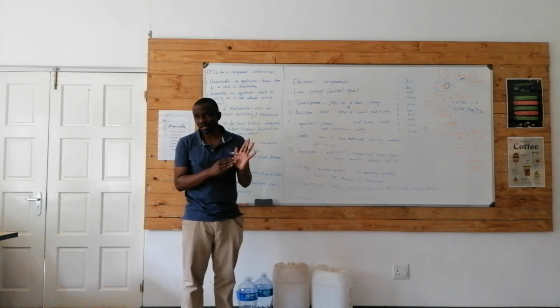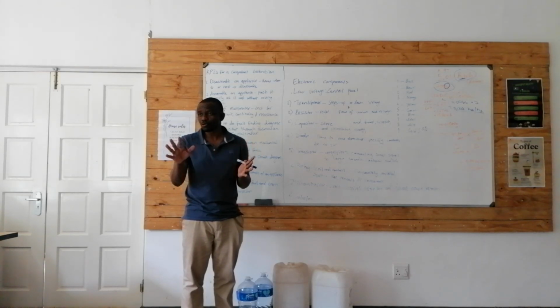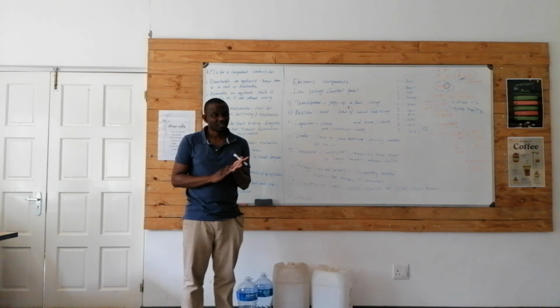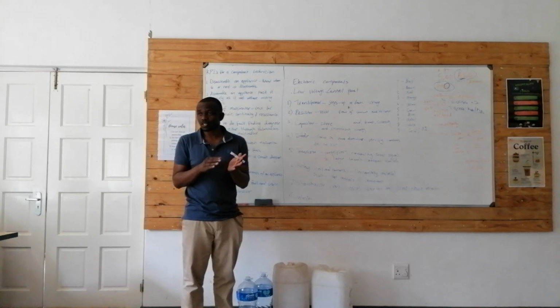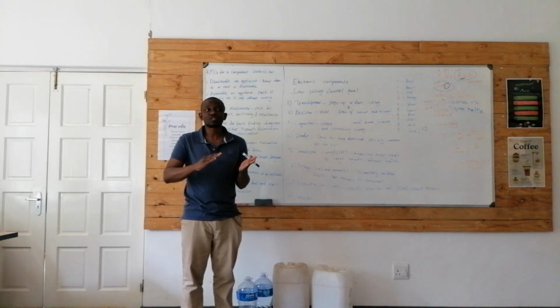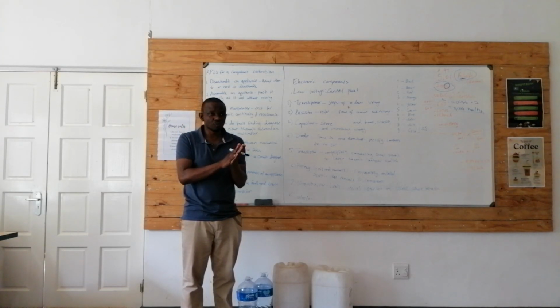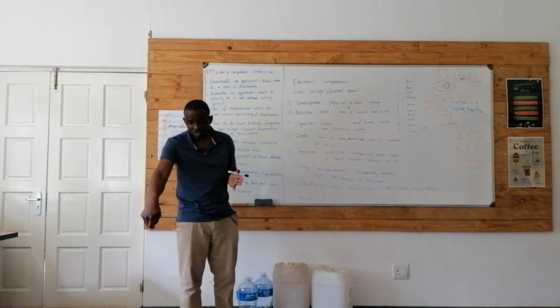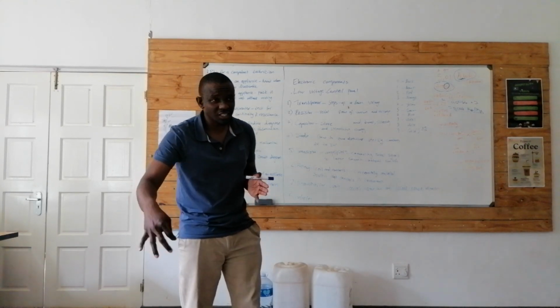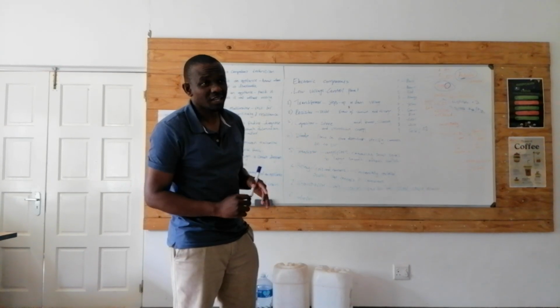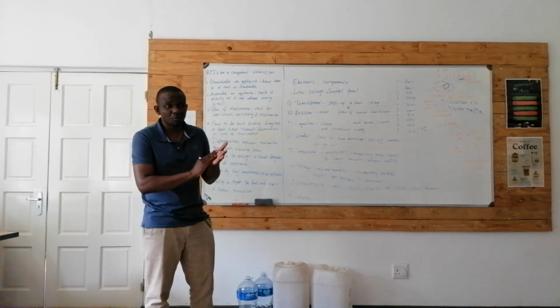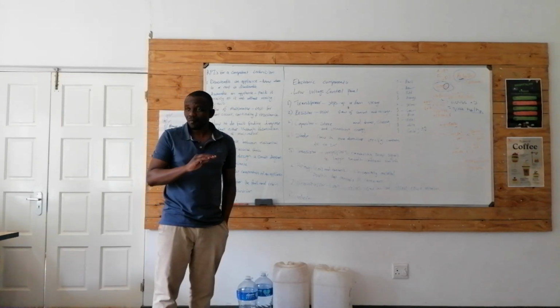Use a small brush and wipe it, or use a damp cloth. Avoid using water because water takes time to dry off. Use something that can quickly dry off. But too much of it will burn the board. So even when you use alcohol on the brush, you have to shake it before you brush, so that immediately when you remove it, it dries.